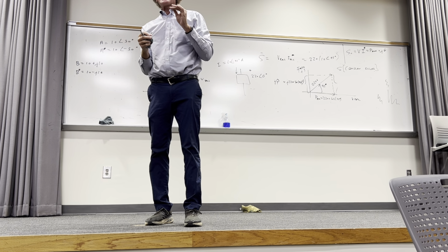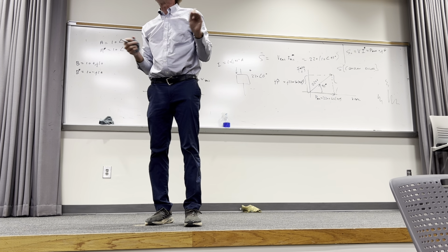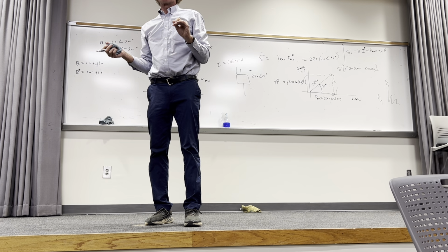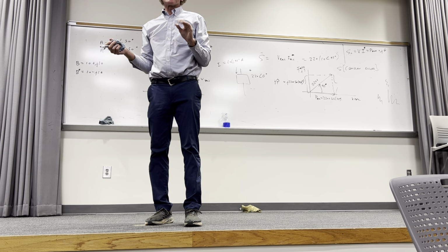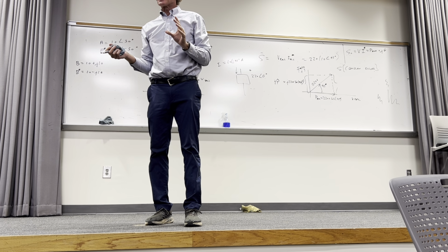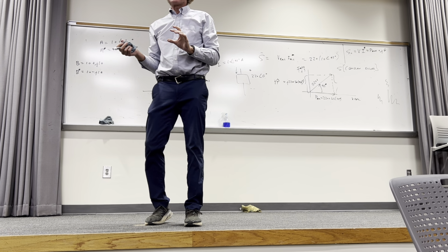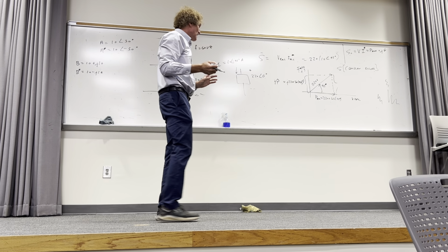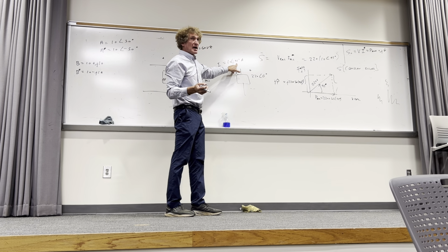Now, the reactive power is something you would like to get rid of. It does no good for anybody. It's just extra energy that has to be provided per cycle to the circuit. You would like to get rid of it, and the way you can is by adding a component, typically a capacitor, to any kind of circuit that's dominated by an inductive reactance, which this one is because the angle here is actually behind it by 45 degrees. Can you all follow me, at least in the ideas?